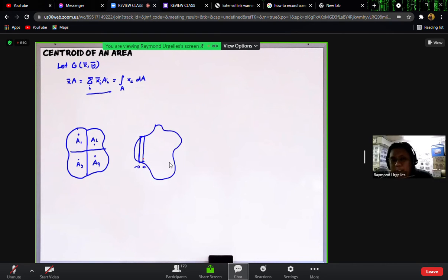When it is a vertical strip, it is very thin, so only its length matters, and its centroid is at the middle. We can even use double integration, dy dx, where the centroid is its position itself. Although for centroids I don't recommend double integration because the equation becomes more complicated. We will use either a vertical strip or a horizontal strip.